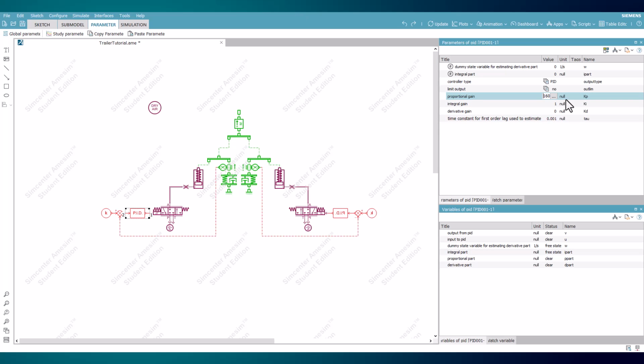The integral gain is a value that allows for the error to become 0, which is not possible with the proportional gain alone, and through batch runs and tests is found to be negative 2000. A derivative gain will assist in damping oscillations when controlling the system, but is not necessary here.